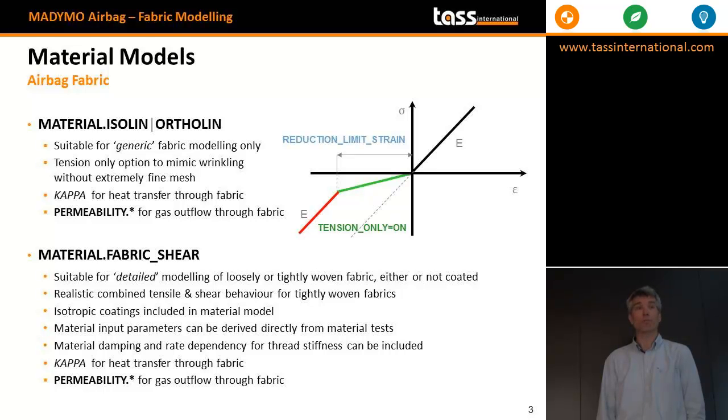That's a user-defined parameter. On top of that you can define kappa. For typical load cases like passenger and driver airbags, this is not that relevant, because the energy loss through heat transfer is not that much. However, for the FMVSS 226 with 6 seconds runtime, this might be important. Typically, a curtain is completely sealed, so you don't have holes and don't have permeability.